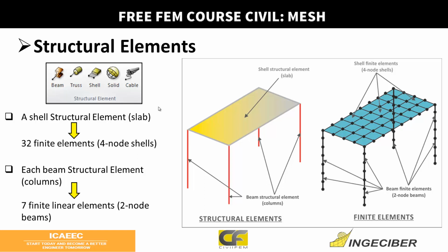We have seen how to mesh beam structural elements and shell structural elements. Of course it will take more time to mesh, but it is still easier than the most general case, which is solids. All these elements can be meshed with solid elements, but it will take more time and the results will not be more accurate. You always have to consider the time of the engineer and the time of the machine. If you want to create a submodel or a detailed analysis, of local buckling or yielding of some connections, of course solid elements will give you more precise results.